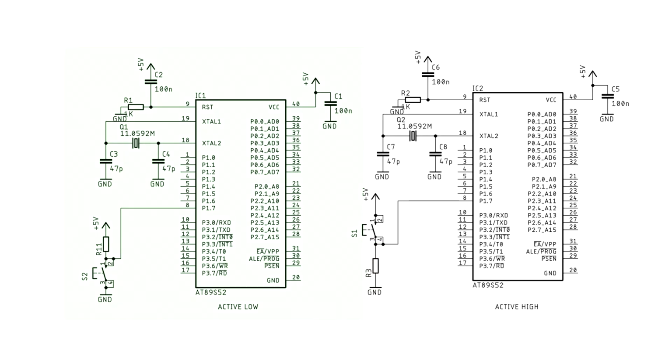Because of the structure of the ports of the 8051, especially port 0, which requires external pull-up resistors, we choose the active low configuration. As a rule of thumb, we choose a resistor in order of magnitude of 1/10 less than the input impedance of an input pin, usually 100k to 1 megaohm. Thus we choose a 10 kilo ohm resistor.